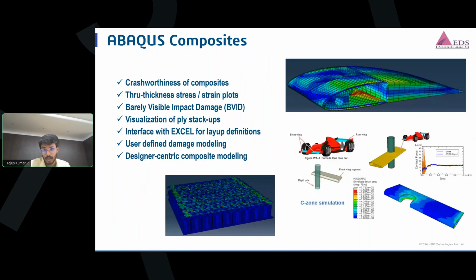Beyond structural analysis, Abaqus predicts damage initiation and propagation within composite structures. Engineers can evaluate impact damage and through-thickness stresses and optimize the laminate stacking sequences before manufacturing, seeing how the stress is transferred from each layer. So if a crack is propagated, you will get to know easily through composite simulations.